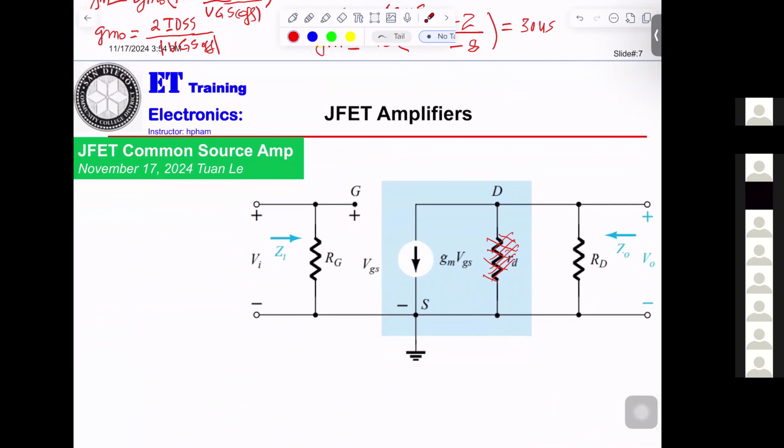Okay. So basically, you got little RD and big RD in parallel. But you're saying, let me finish, you're saying the magnitude of little RD is so big, it's insignificant. So that's why you just go with big RD only. Exactly. It's like if you put two resistors in parallel, and one of them is 100 ohms and the other one is a billion ohms, it's going to take the smaller one.